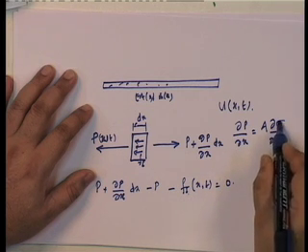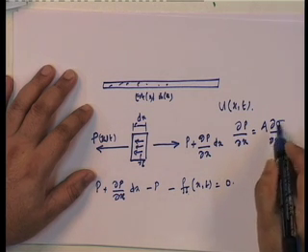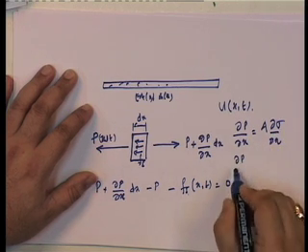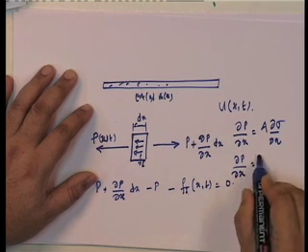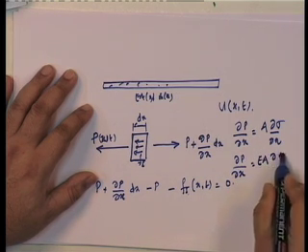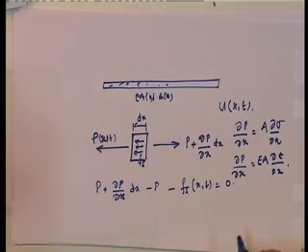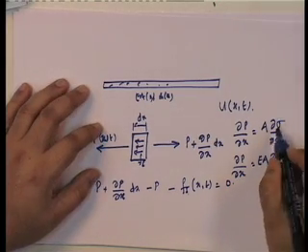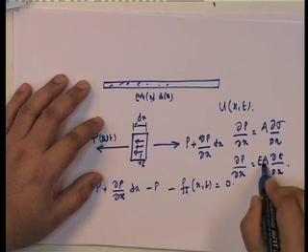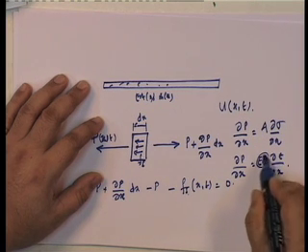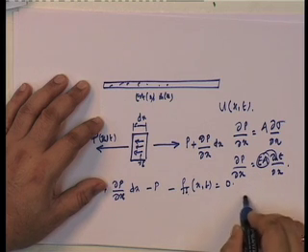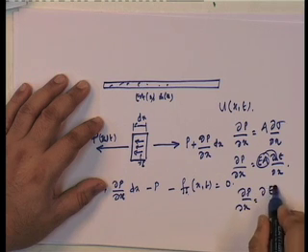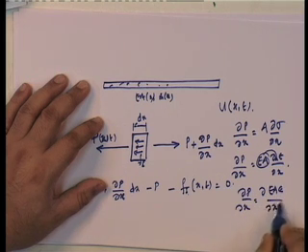Now, del sigma is equal to E del epsilon by del x. Actually, no, because A can also be a function. So, these go inside, and it becomes del P upon del x is equal to del of E A epsilon by del x.